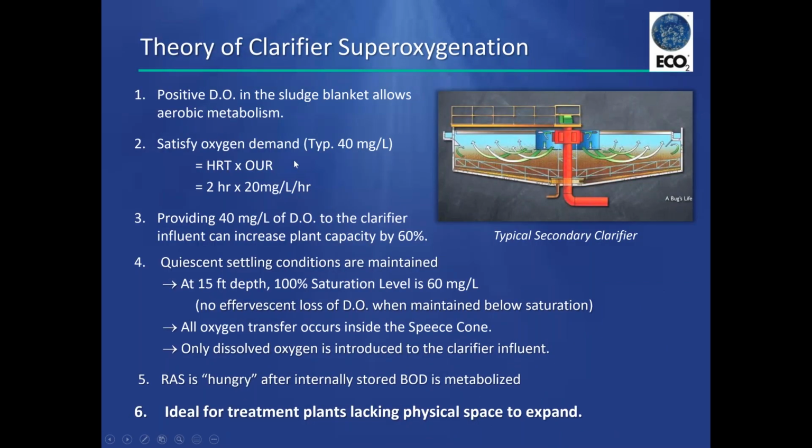So it's going to vary, whatever this oxygen uptake rate is in the sludge blanket. At the head end of the aeration tank, there might be an oxygen uptake rate of 100 milligrams per liter per hour with the readily degradable food coming in. And at the head end of the aeration tank, a lot of the BOD is taken out rather quickly by either attachment of the colloids to the biomass or taking inside the soluble compound.